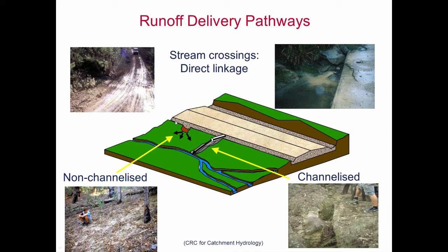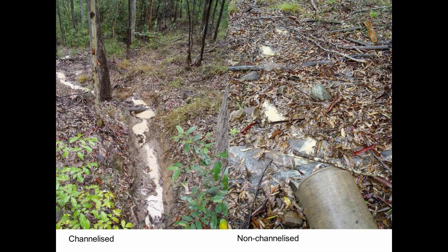So just to picture the channelized and the non-channelized options here. On the left-hand side, this is below a relief pipe. You can see that a gully, right beneath where my feet were, has been created at the outlet of the pipe that has taken water from the road, and that gully extends all the way to this stream.